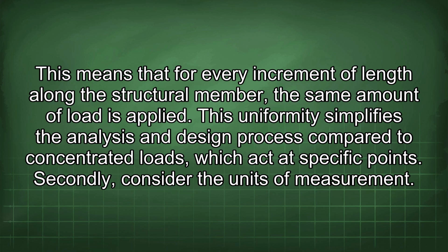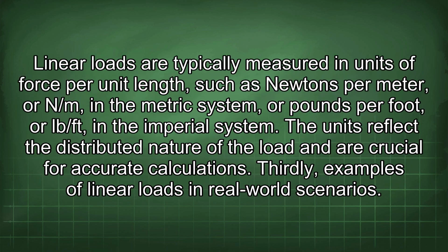Secondly, consider the units of measurement. Linear loads are typically measured in units of force per unit length, such as newtons per meter, or N/m, in the metric system, or pounds per foot, or lb/ft, in the imperial system. The units reflect the distributed nature of the load and are crucial for accurate calculations.